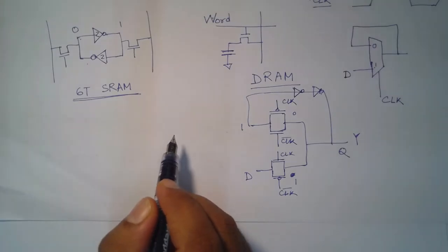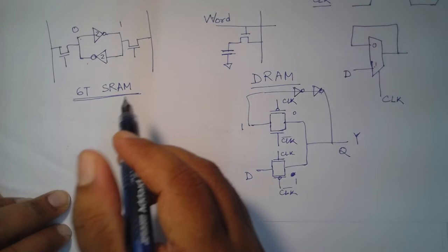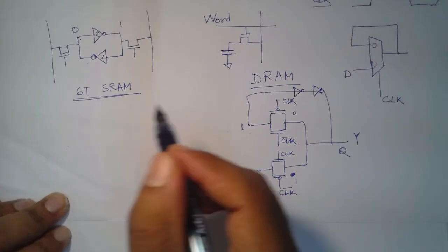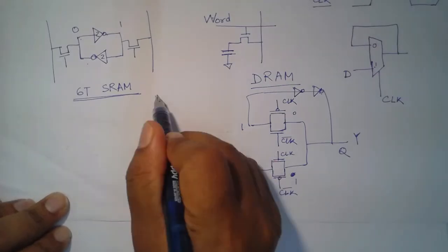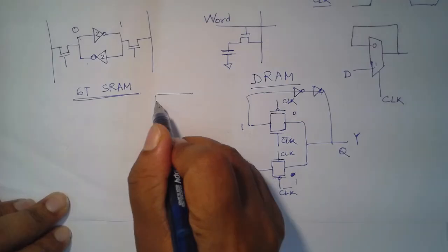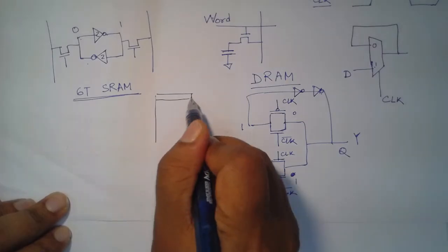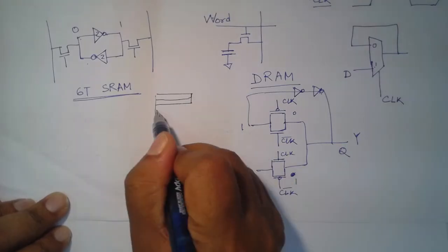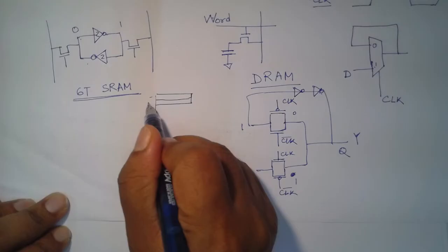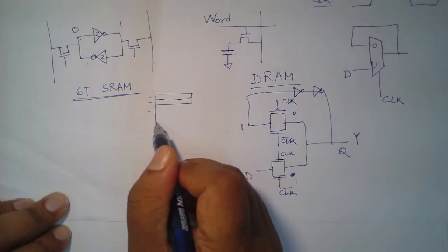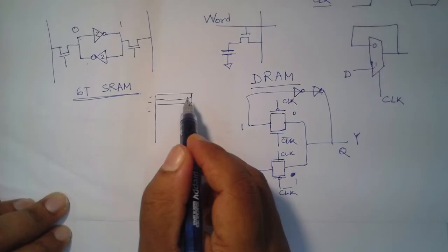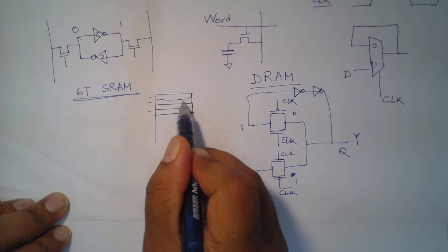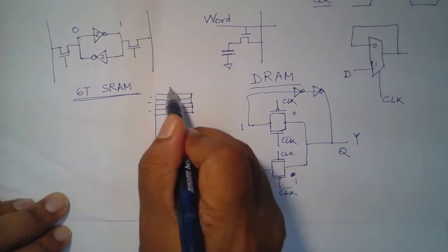Now, each word I am dealing with is 32-bit. So, if I decide to store or design my memory in such a way that, let us say, this is my memory, and each row of the memory stores a 32-bit number, and whenever I need to read this specific row, the addressing will tell me which row I need to read depending on what data I am looking for, and I can basically design my memory such that each row is storing 32-bit.